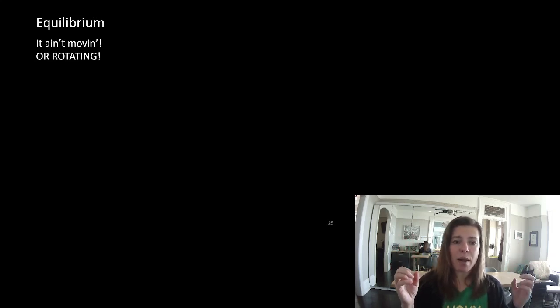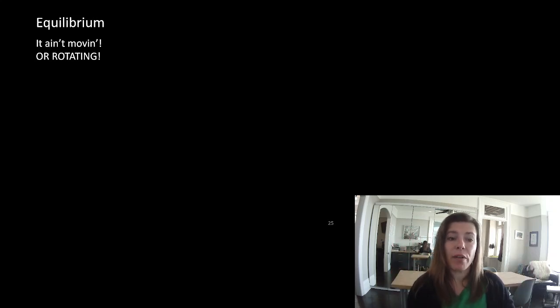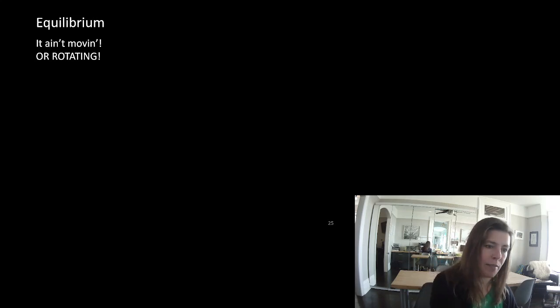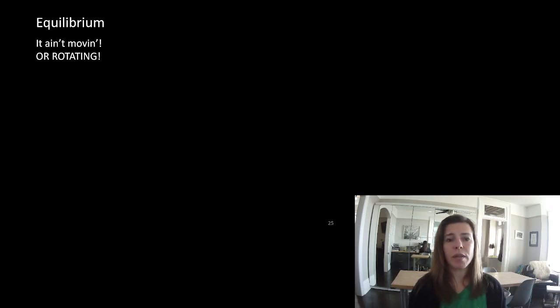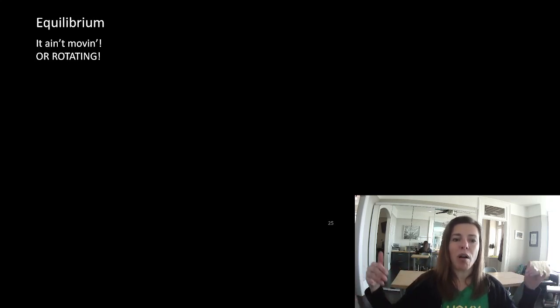And if I do that by assuming my columns are the reactions at the end, I can figure out how I design my columns. So we figure out the load on the beam, design the beam. Then we figure out what that does to the columns, and then we design the columns. Then we figure out what the columns do to the foundation, and we design the foundation. And then we figure out what the soil does as part of that foundation design as well.